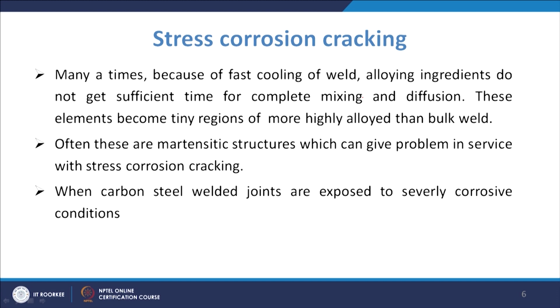They dissolve in the weld pool, but cooling in welding is fast for many reasons, as we have studied so far, because of the presence of metal on both sides having higher thermal conductivity. So, you are getting less time to properly diffuse, mix, or distribute.